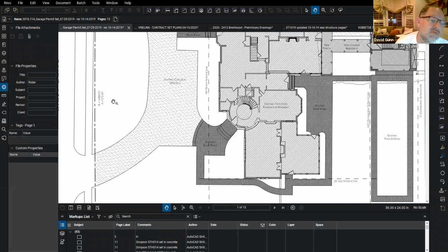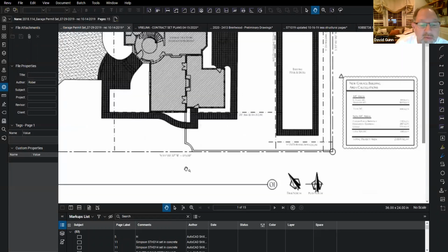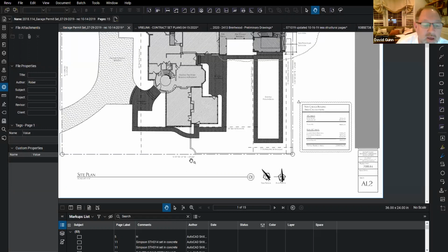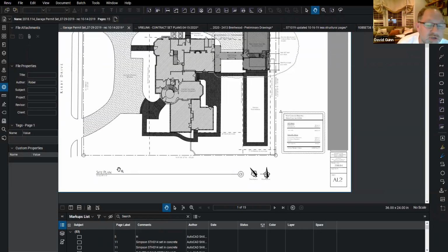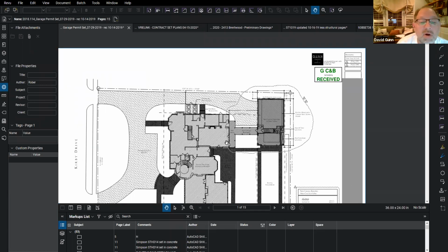For example, this survey, if I look up here across the front, shows that that front line is 125 feet across. So that lot is 125 by 175 on this side. And it gives some coordinates, you know, it's survey talk. But it also shows the property corners, which is important to us when we start laying out a building. That's these big circles. On each corner, this corner, that corner has a circle, that corner has a circle, and that corner has a circle.